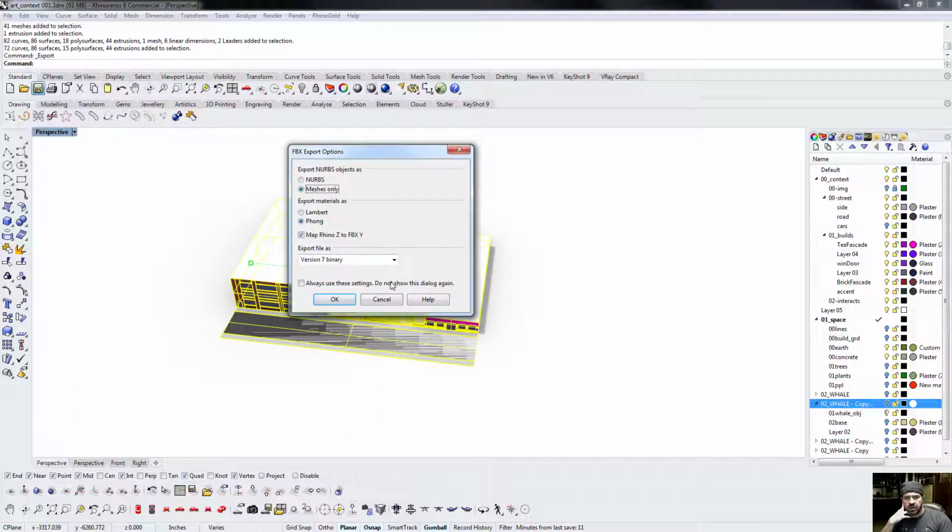But you should know this setting here, which is mainly for importing and exporting in Cinema 4D, Max, any of the big animation softwares, typically uses Y as the vertical axis, and Rhino uses Z. This setting is automatic when you come into Twinmotion, so we don't really need to worry about it. I just keep that right where it is.